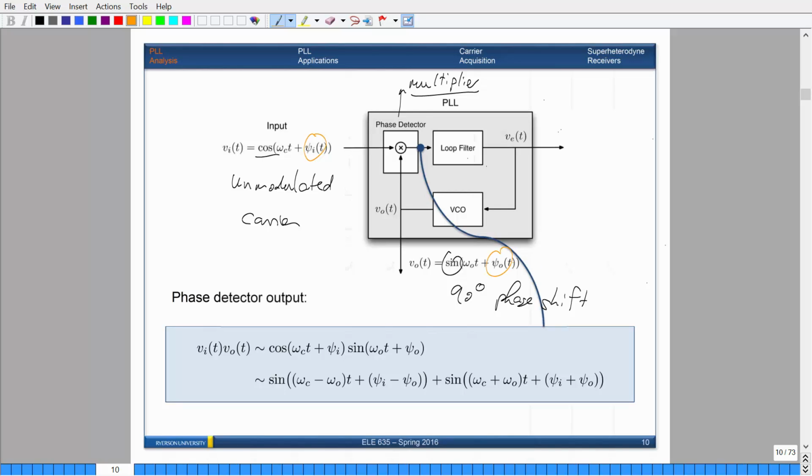What these are is that, due to some noise, there may be a point where you may not exactly be able to get the right carrier frequency. For example, if your carrier frequency is 5 hertz, somewhere down the road there might be some noise that will change it to maybe 5.2 or 5.3. Those tolerances are covered by phi I of t. So it's basically all of the things that are introduced that will make it not equal to your desired carrier frequency.